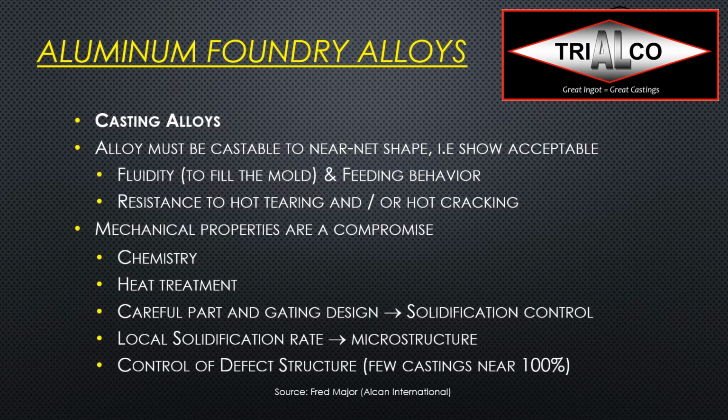So that will determine the microstructure. And last but not least, control of the defect structures, because very few castings are completely porosity free, although sometimes you see this on a drawing that specifies that the casting has to be porosity free. So unfortunately, that is normally not possible.